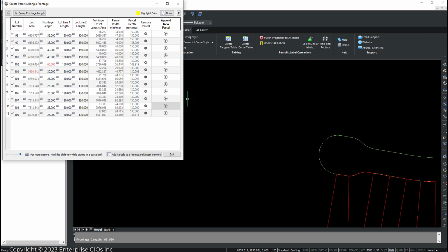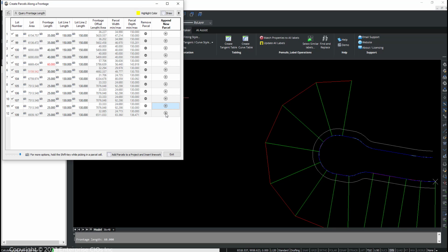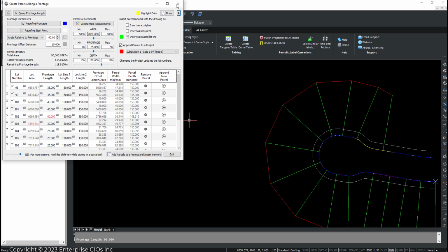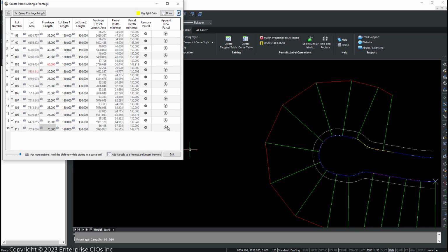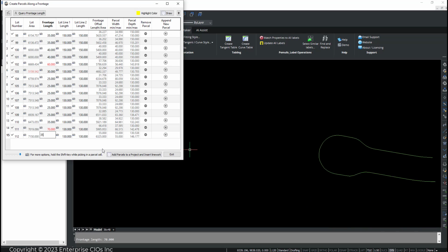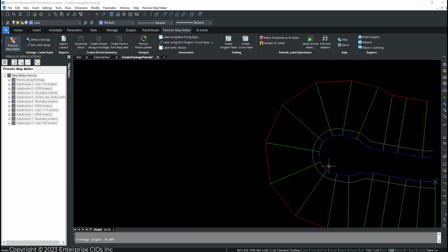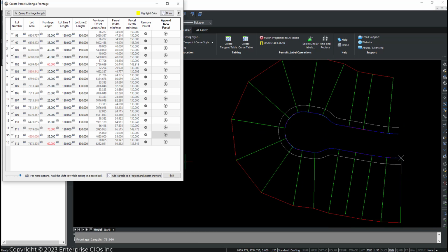And let's just see. Okay, now what's going to happen? It's calculating the values, and it found that it had to exceed that frontage length in order to put a lot in that's close to our desired 7,000 square units. And then let's just keep adding lots as we go around. I'll make this frontage 35. That changes our minimum, our lot calculation, and hit plus.